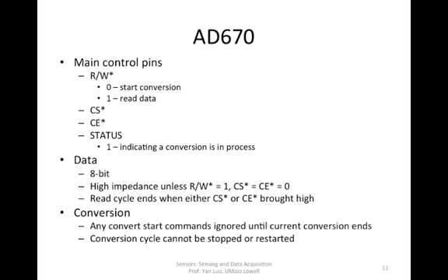Read cycle ends when either CS or CE is brought to high. For the conversion process, any conversion start commands will be ignored until the current conversion ends. So you cannot interrupt the conversion process.